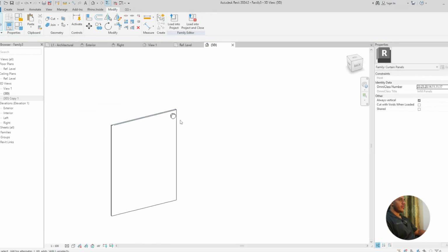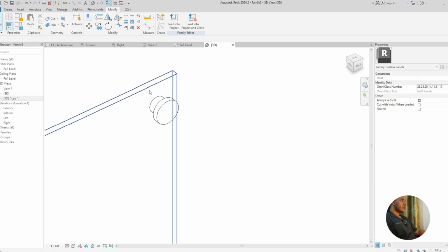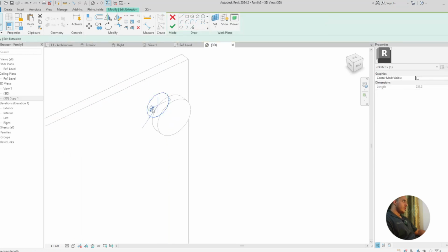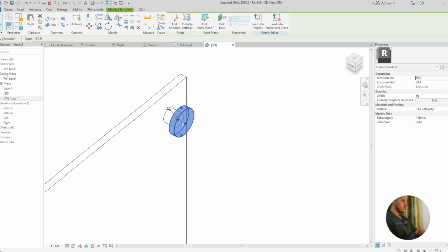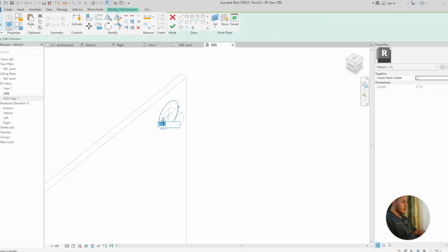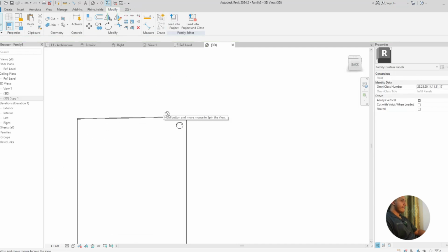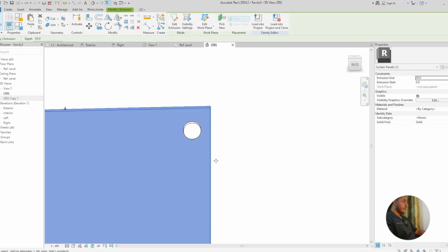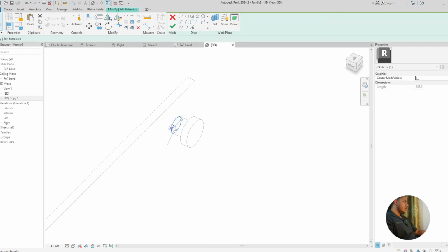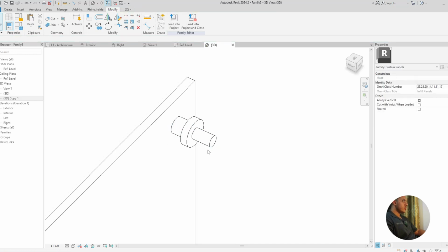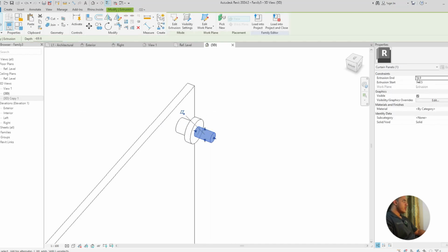Just keep in mind this is just a basic family to follow in a concept stage. You need to re-enhance and readjust if you want to work with it as a BIM model. So this is just a basic element spider. And I'm going again to duplicate this element object and drag it up, attach to bottom, reduce the radius to 20. Okay, then